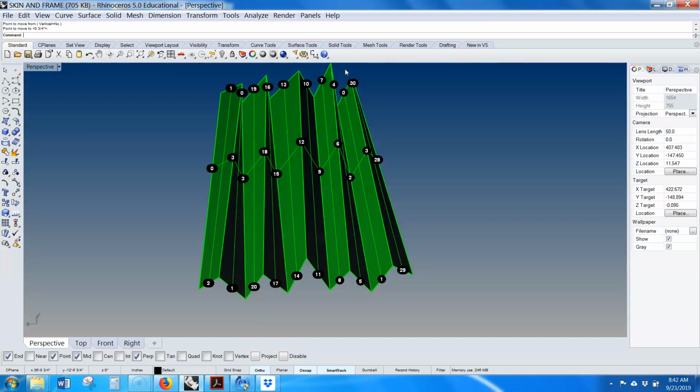Again, guys, remember, what do we tell you with your labyrinths? Anytime you go into 3D, don't just extrude to get to 3D. If you just loft the same curve, you don't need the other curve. You're just extruding one curve. The nice thing about loft is you can take two completely different curves, and it's called interpolation. You're modeling by filling in the differences between those two curves, and it gives you a more complex set of shapes and forms that you can experiment with. And that's what 3D modeling should be used for.